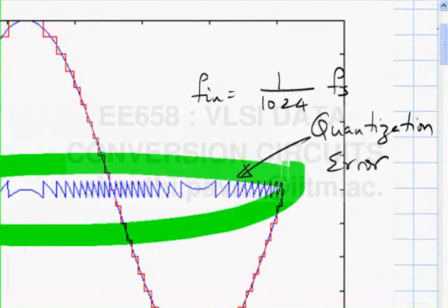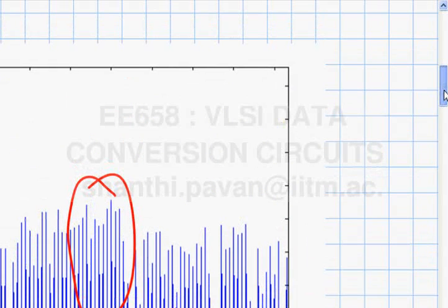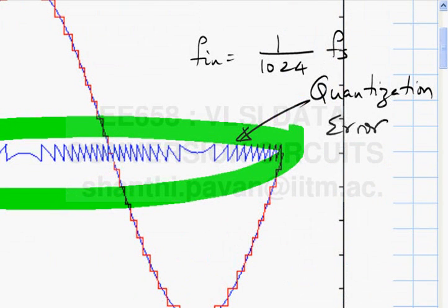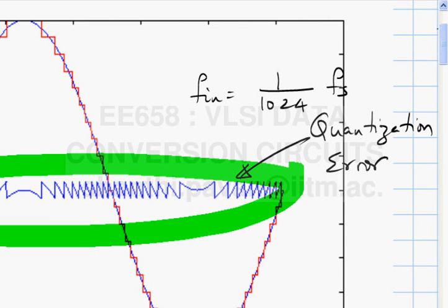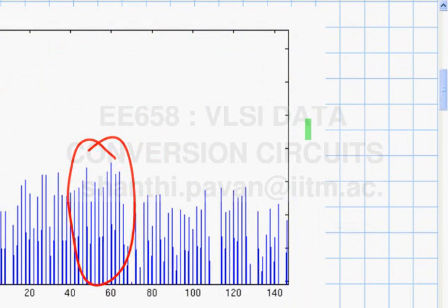And we were trying to build intuition yesterday about how the quantization spectrum should look. One piece of intuition we got was that if you stare at this waveform, it looks like some kind of FM waveform with some average frequency. We counted the number of times this triangle jumps up and down, and said that it must have significant harmonic content between about 45 and 55. And lo and behold, when you do the Fourier analysis, that's what you see.